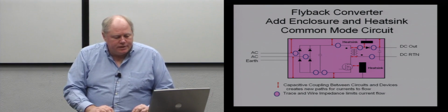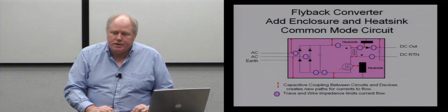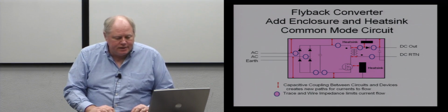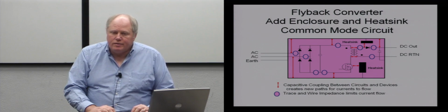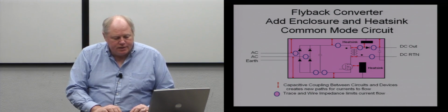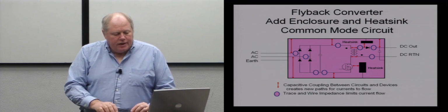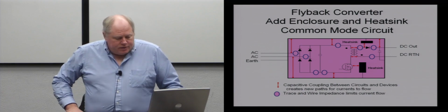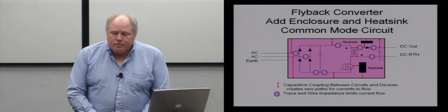One of the ones that's a real common one is you have a FET and you need to bolt it to a heat sink. A heat sink is like a great big plane. You get it very close because you want to transfer the heat. It's not electrically connected to the heat sink usually, but sometimes it is. And the voltage on the FET is going to be going up and down several hundred volts.